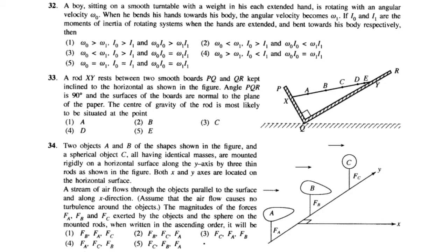And you can see that two forces meet at a point. So we say that point is O. Now, for the equilibrium of the rod, all the forces which are not parallel must go through one point. So two forces are meeting at one point at O, and the other force, which is the weight, also must go through O. Now you draw a perpendicular line to this horizontal surface. That line will go through D. So D is the center of gravity of the rod. Answer is 4.